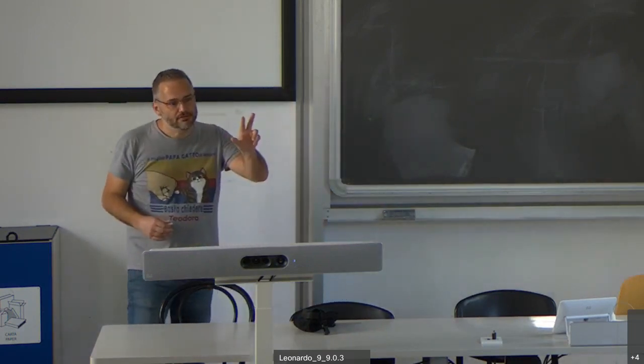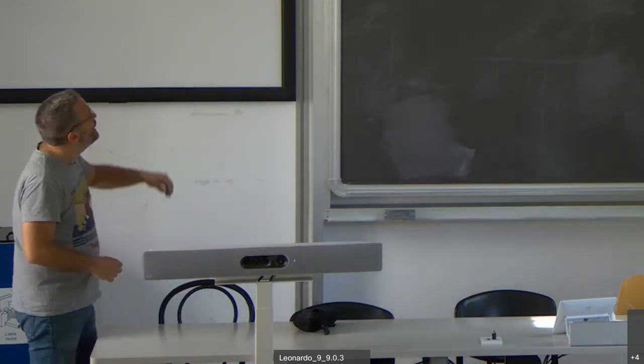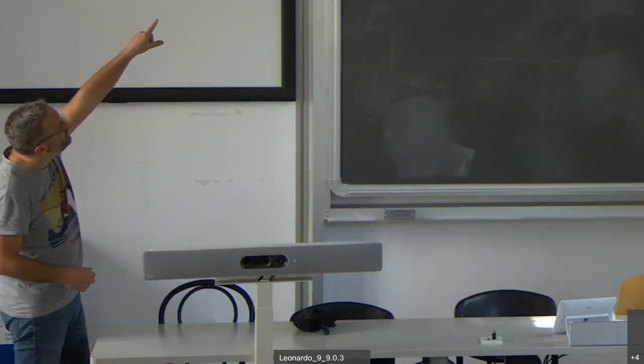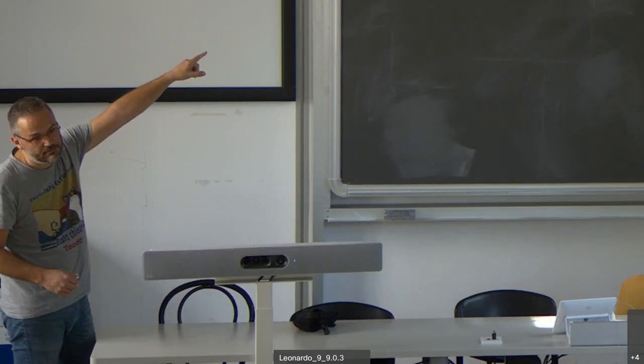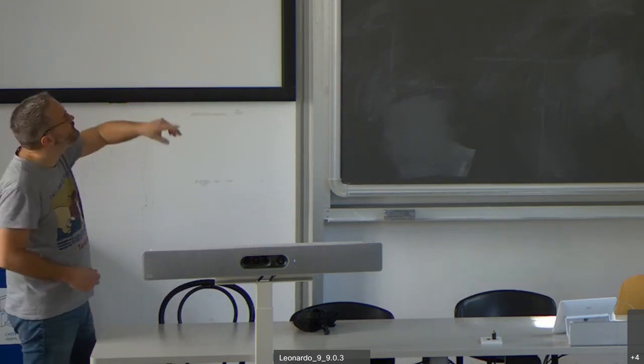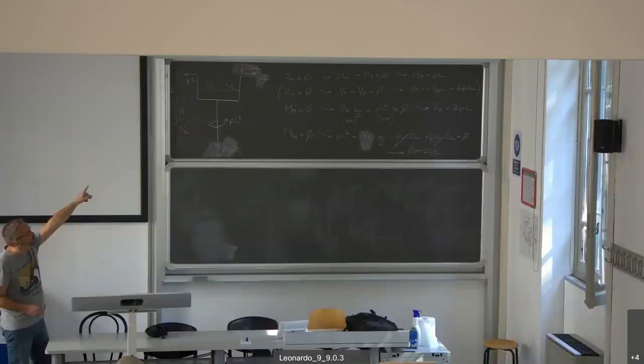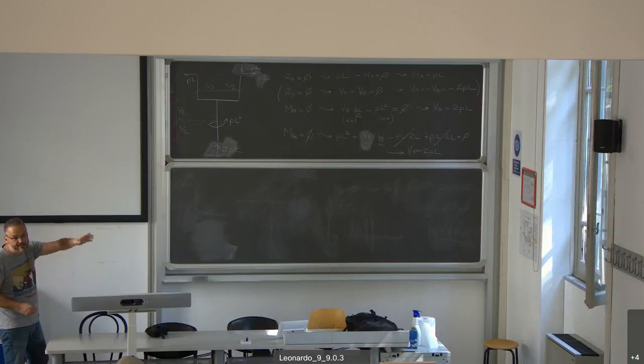Third observation. I will start from the left portion of the structure, just to show you that whenever you have a free end, and the point at the top left is a free end, where you know the load applied and nothing else, you don't need to know the rest of the structure.